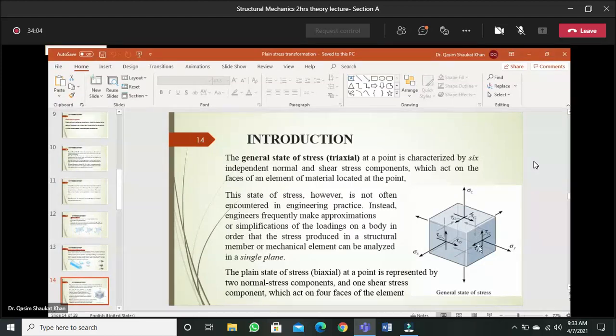First, let's designate this shear stress and this shear stress. It is acting on the y plane, and this stress is acting towards the x. So it is basically tau yx. Then, in fact, we should start with this. This is exactly the same as our sign convention.